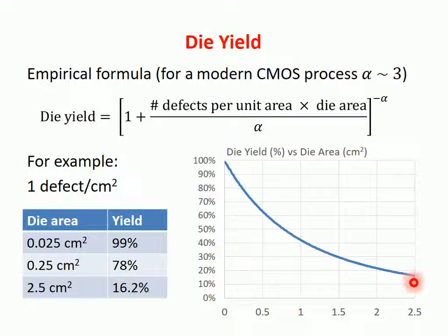Of course, if we want to make and to sell with profit a microprocessor with 2.5 square centimeters of area, of course you need to have much less than 1 defect per unit area. Okay, you need to move quite up to the 70–80% range. Okay, but this one is typical of many processes. For example, it's typical of the processes that we use in fab in Taiwan for designing chips. Okay, but we have all the elements that we need to be able to evaluate the cost of a chip starting from a set of numbers, and this is done, of course, continuously in order to know what is the break-even point in the selling and in the production of a chip.